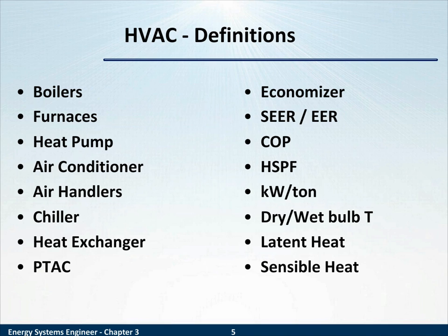Is the seasonality in London the same as the seasonality in Phoenix? The HSPF, or the Heating Seasonal Performance Factor, is the measure of a heat pump and its efficiency during heating. It's a seasonal measurement like SEER, but it's a heat pump during a heating seasonal performance.